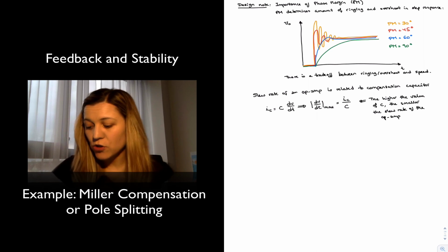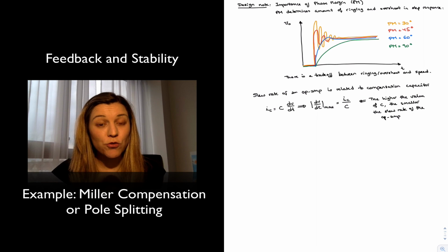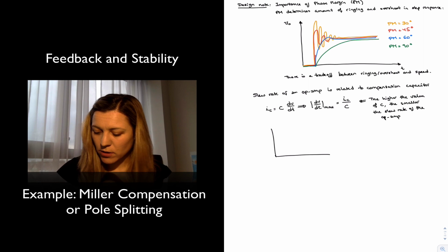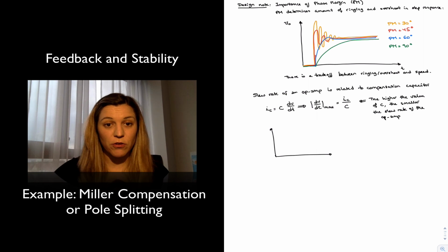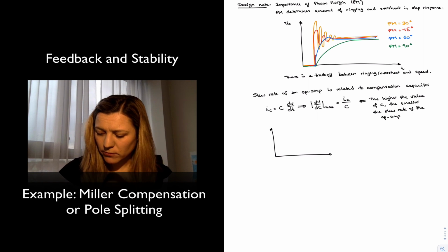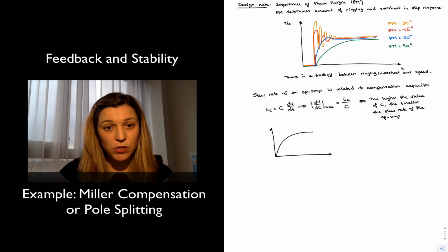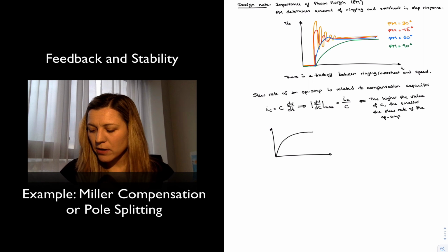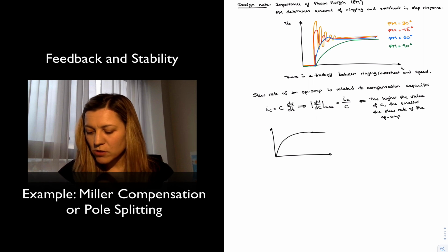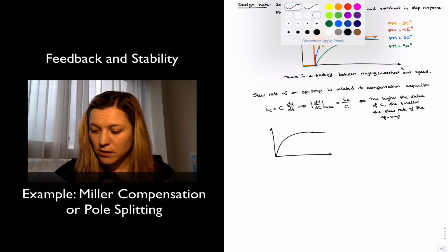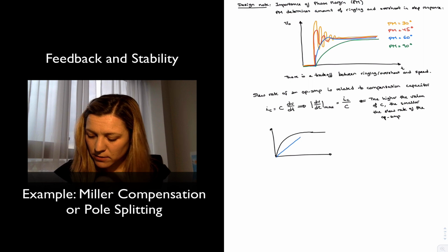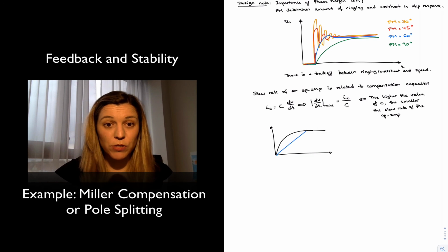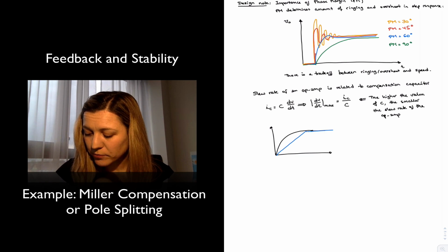Notice also that this also explains that nonlinearity in the slew rate. In a linear system, we will expect that just like the charging and discharging of a capacitor, you expect to see a rounded response like this, just because of the equivalent of a low-pass filter. However, when you're seeing the slew rate of an op-amp, what you see is a nonlinearity, let's say in response to a step response, until the op-amp is able to reach that final output voltage.